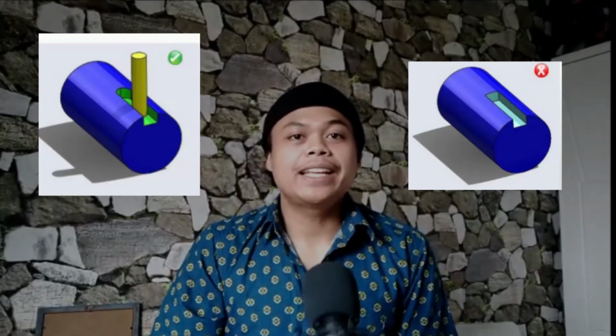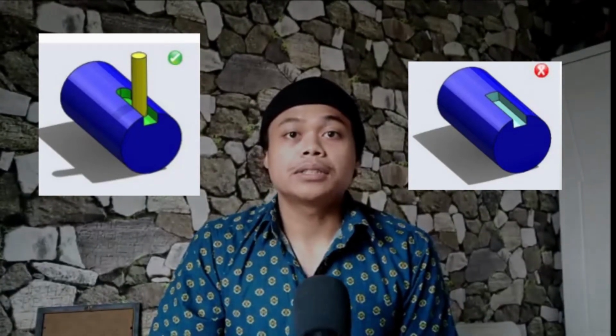Design features to facilitate keyways. For generating external keyways, an end milling cutter or slotting cutter has to be used, and it can be done much faster compared to other processes. To suit a cutting tool, a blind axle keyway should be radiused at the end. Width of the keyway should be such that a standard cutter can be used. If the end of the keyway is radiused in such a way that it could be cut by a slotting cutter, it will improve the speed of machining keyways.